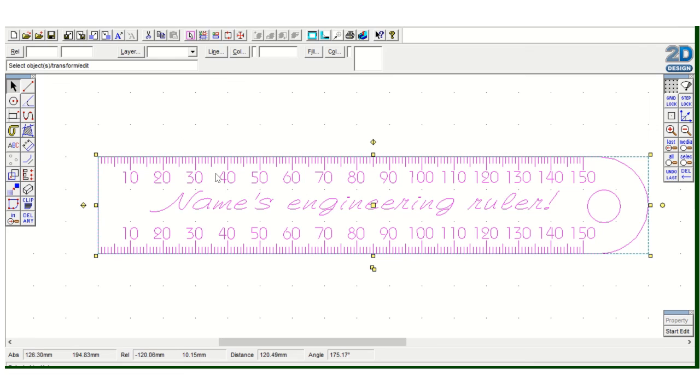The next thing we'll do is highlight all of it, highlight the complete ruler, all of your working that you've just done, and you will again select the right mouse click. That will deselect. So if you've just deselected now all your red engraving work, you're just left with all the remaining lines, which are all the cut lines.